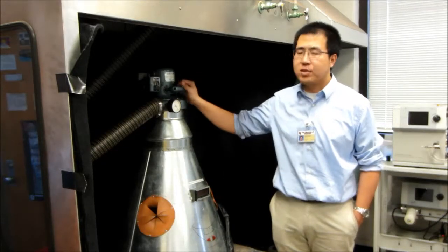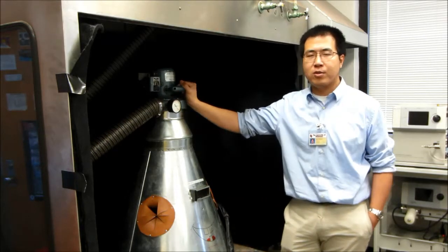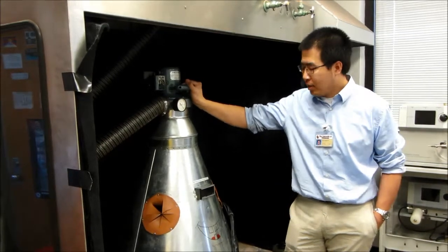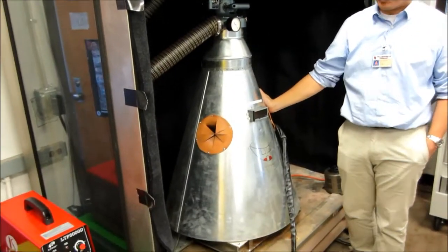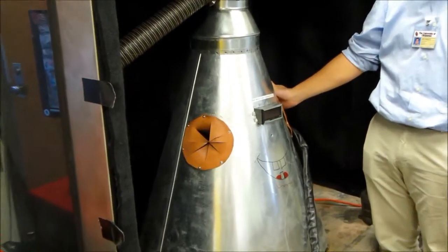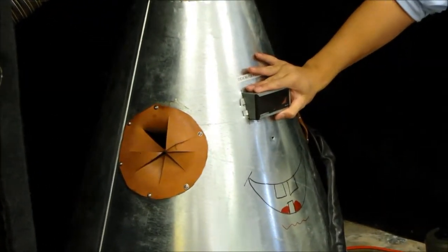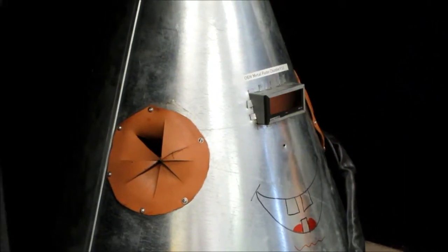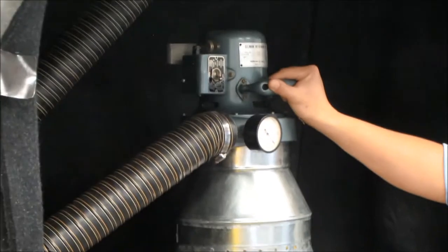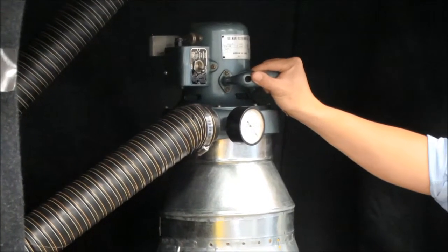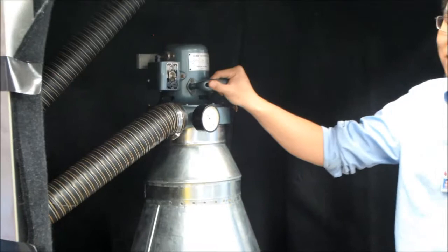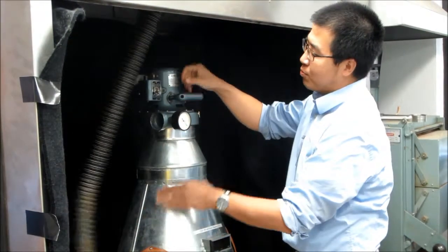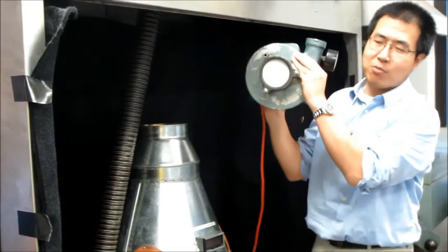A conical metal fume chamber was constructed according to American Welding Society F1.2 2013 specification. There are two glove holes on each side of the chamber, which allow me to operate the plasma cutting. The tinted glass acts as an observation window. The sampling inlet here allows the particle size measurement and particle imaging. The Gilian Hurricane air sampler is able to create up to 2 cubic meters per minute airflow. In this study, it's configured at 0.5 cubic meters per minute. The air and the fume will be drawn through a 90 millimeter glass fiber filter.